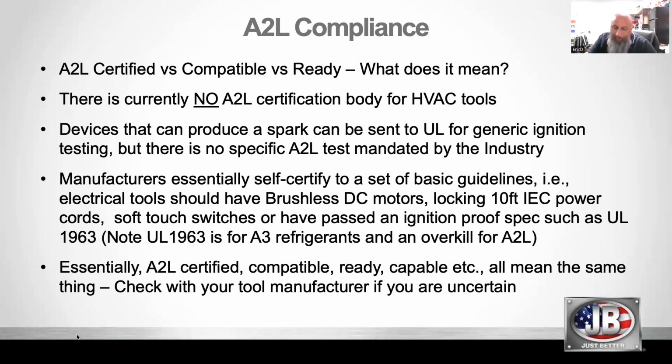And that goes back to what I was saying right at the beginning about liability. Somebody's going to evacuate a system which has got no refrigerant in it, but he's got 4 tanks of propane right around the corner, a couple of feet away, and something's going to blow up and there's going to be a liability issue. And it'll come down to warranties with the equipment manufacturers as well. So you go back with a warranty claim, and the first thing they're going to go through is a little bit of a checklist with you, right? Did you follow these standard procedures? Did you use A2L compatible or A2L certified tools? And those are standard things that people ask when they're trying to wiggle out of a warranty claim.